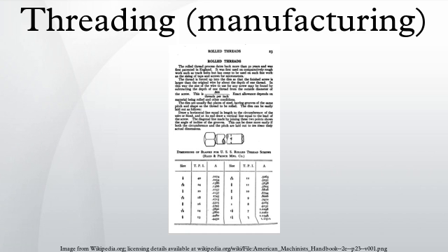Additive methods. Many, perhaps most, threaded parts have potential to be generated via additive manufacturing, of which there are many variants, including fused deposition modeling, selective laser sintering, direct metal laser sintering, selective laser melting, electron beam melting, layered object manufacturing, and stereolithography. For most additive technologies, it has not been long since they emerged from the laboratory end of their historical development, but further commercialization is picking up speed.